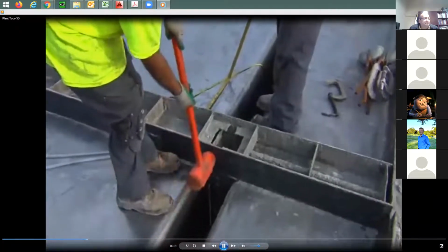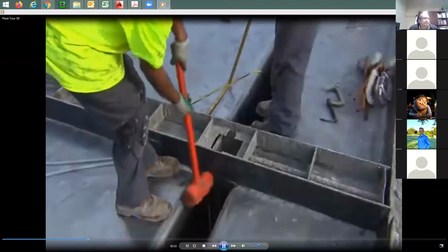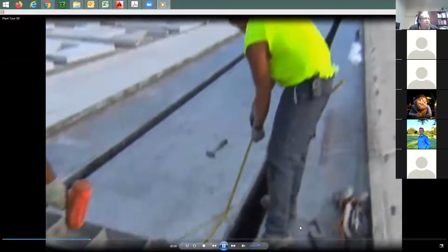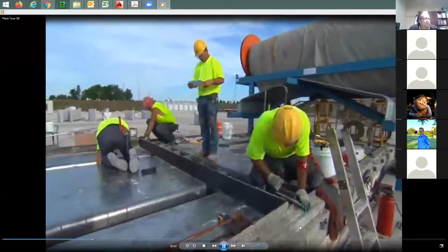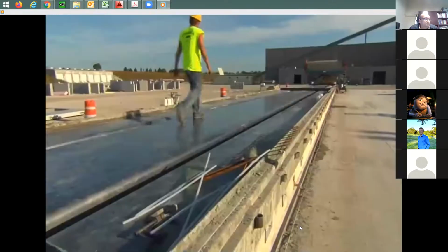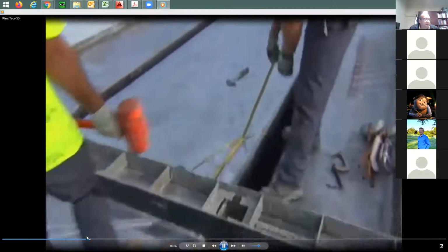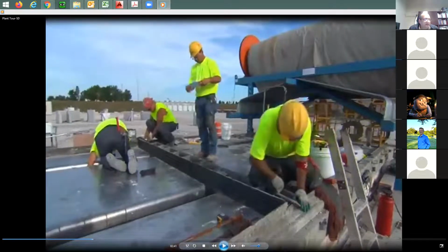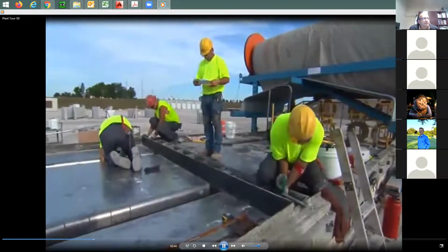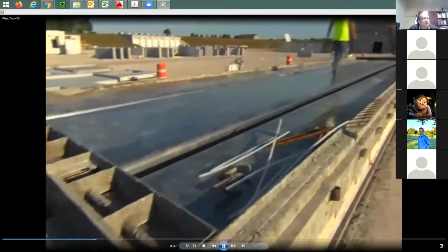This divider is a steel device that separates the individual double T units from one another. A gap of about a foot is typical between the ends of the adjacent pieces. This gap is required so the strands can be accessed and cut, and that each double T can be stripped from the forms. The strand is going to be continuous, right? And then they're going to come here and just trim it. They're going to do this after the concrete is hardened, with a small grinder.